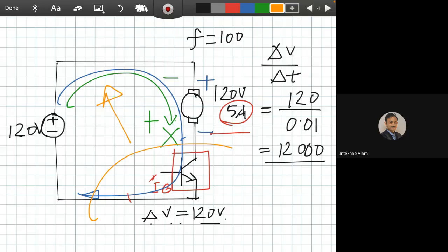If you consider a boost converter, can you recall that we have an inductor here, a switch here, and a diode here? Can you recall this circuit? Whenever we close the switch, there is a current rise here, and whenever we switch off, the voltage here is much higher, plus L di/dt.